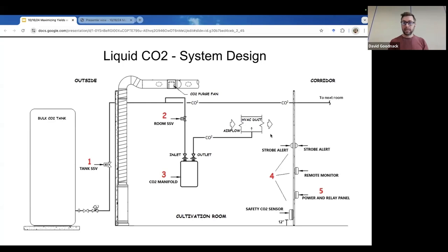Best, in my opinion, would be an under canopy airflow system. This is blowing air from underneath the canopy, blowing it up. It's disrupting the little micro boundary layers, as well as distributing CO2 exactly where the plants are going to be trying to absorb it. So you want that to be the highest concentration.